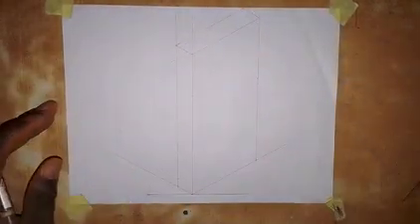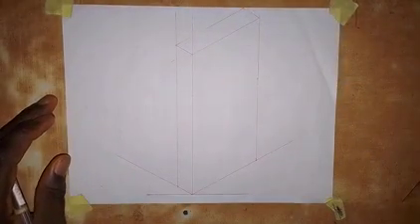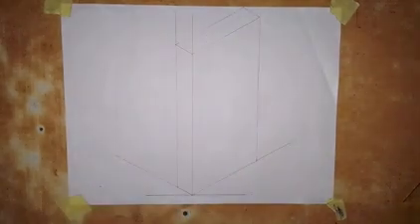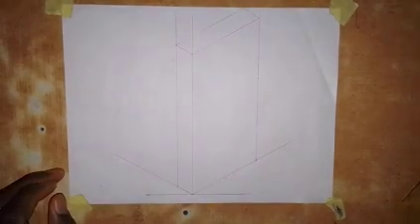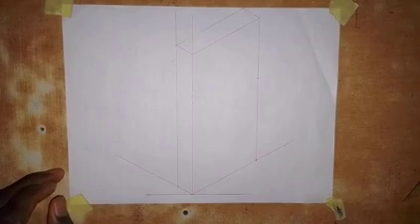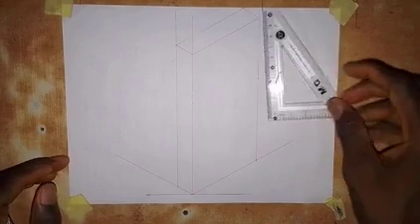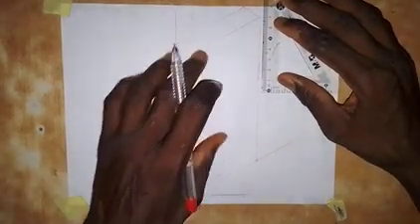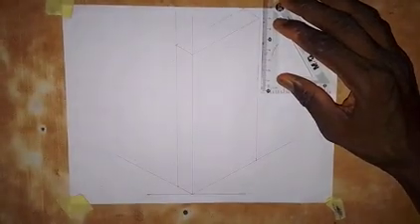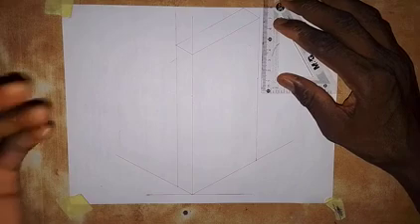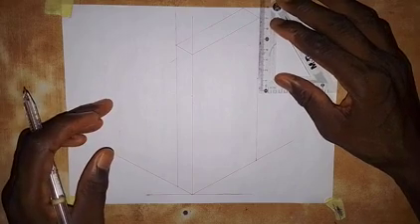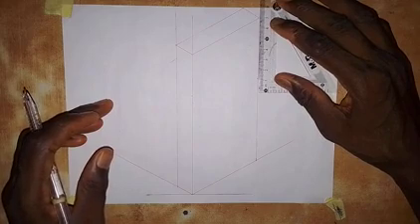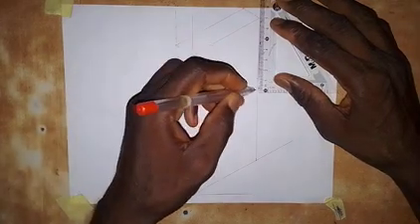Alright, having done this, the next thing that we are going to do is to draw the curve that we have here. And we are told that the radius of that curve is 35. So this is how I do it. I'm going to create a square on this face, because whenever we have to draw an isometric circle, an isometric curve, we draw it in a square whose length will be equal to the diameter of the circle.